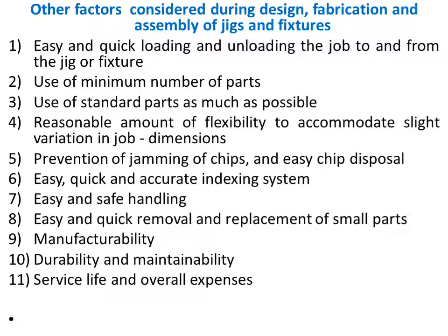Then use of standard parts as much as possible. You have to use standard items like screws or clamps or any other item. You have to use the standard items available in the market. Then a reasonable amount of flexibility to accommodate slight variation in job dimensions. In the previous diagram, we can find that there is some extra space available inside the fixture, so that even with a small variation in dimensions of the component, you can accommodate it very well within the space available in the fixture. Then prevention of jamming of chips and easy chip disposal.